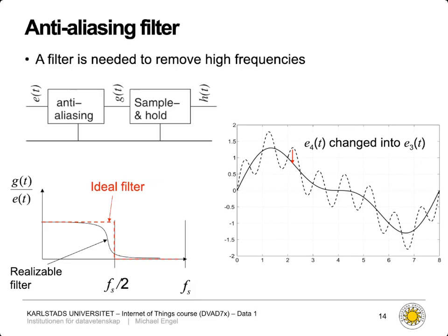So essentially this anti-aliasing filter does not magically add information about high frequencies. That's physically impossible. It just removes these to ensure that whatever we measure is in the frequency range we expect. So this is very useful when you have high frequencies, for example, due to electromagnetic interference coming in, which you want to filter out because they're not actually part of the original signal. And if you would also measure them here, you would get aliasing effects, and that would change your measurement outcome. So these circuits are very useful to have.